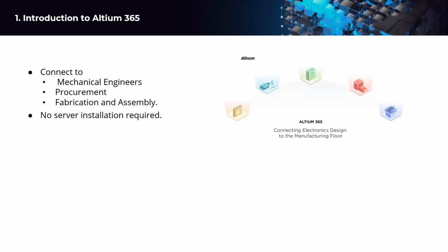So I finish my design, I want to release the design. So you can release it online to Altium 365. Once you release it in the web browser, you can go there and share your file to the manufacturer. When you share the file after release, it will have your Gerber file, NC file, assembly file, then PDF file. All this you can share to them, so that the manufacturer on the other side does not need to have the software. He can just sign in with your Altium Live account to Altium 365.